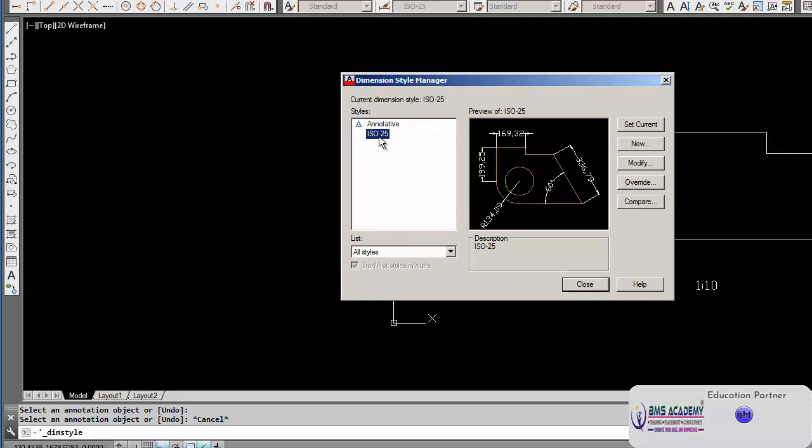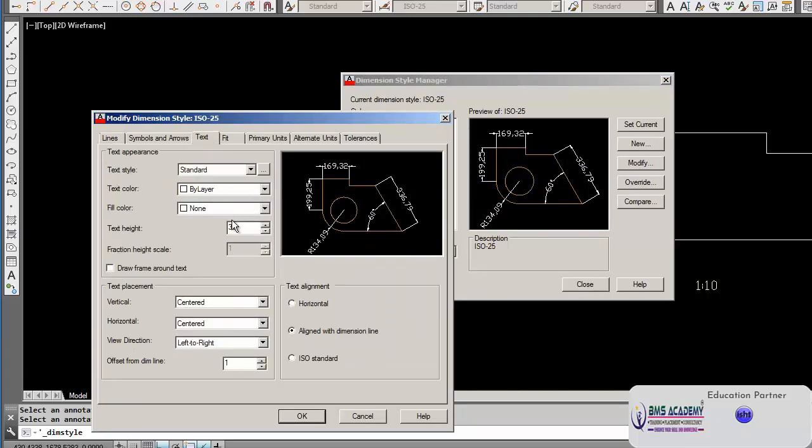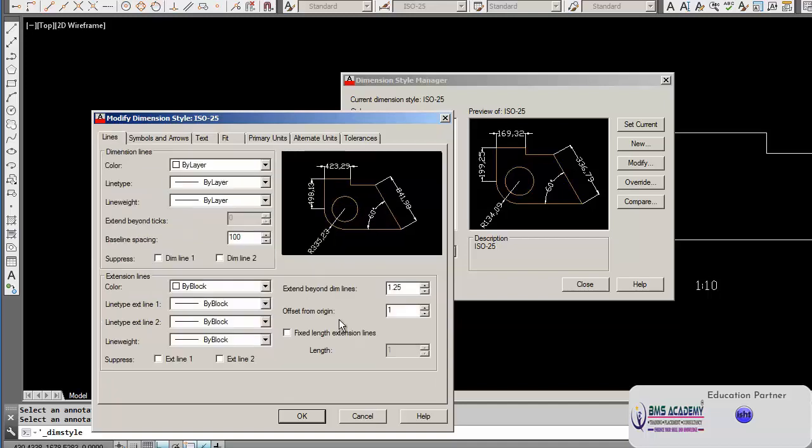And the other one, here, this we modify. This we modify to height 75, and everything we modify proportionally. This we may take as 60. Line here also is proportional to be changed. Extension will make it around 2.5, and dimension from the origin, it's a 2. The extension beyond dimension, then we'll say 1.